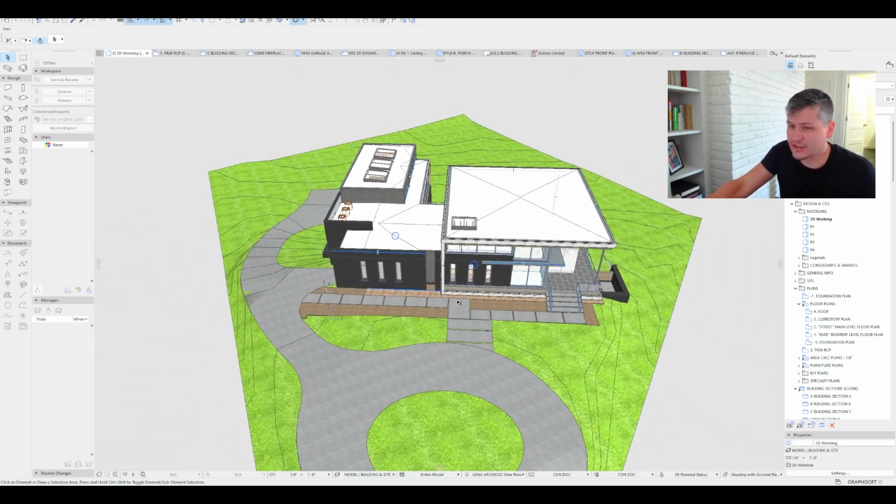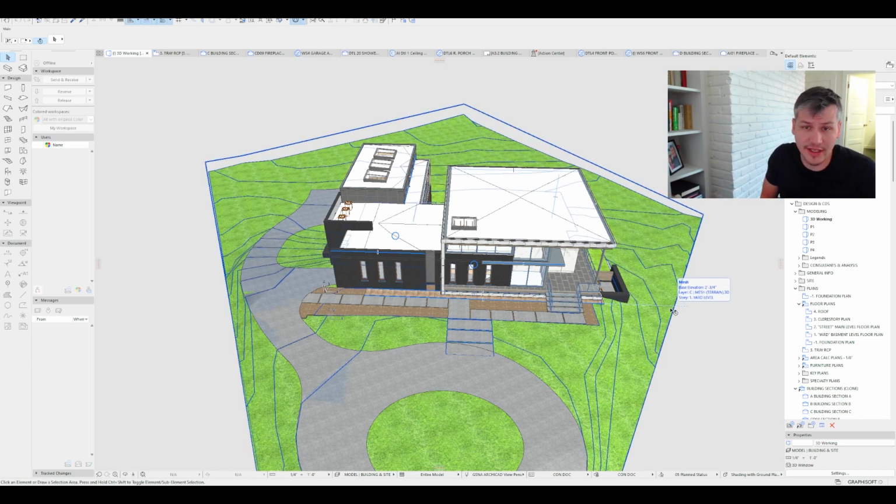But let's just zoom out for a second and talk about the overall. We don't have the whole house in glass, so we don't have to design a steel frame for the entire house. And that was part of the initial conversation, is perhaps we split this into two different types of construction. Maybe on the right side where there is glass, we're going to use steel frame, and then on the left side, we can probably just use standard construction, standard residential construction, studs, sheathing, that kind of thing. That's ultimately going to save the client money, and if you don't need it, you don't need to build it.